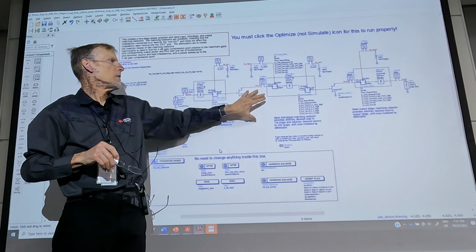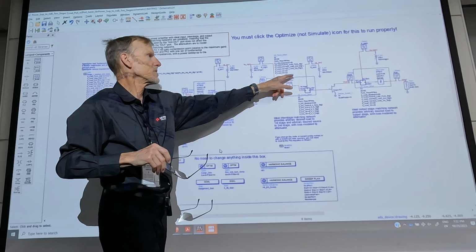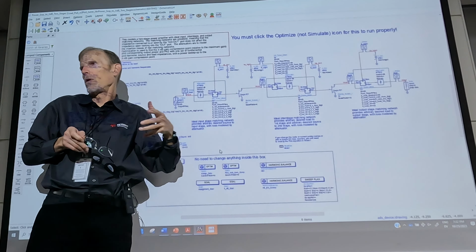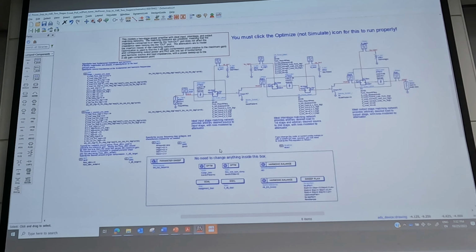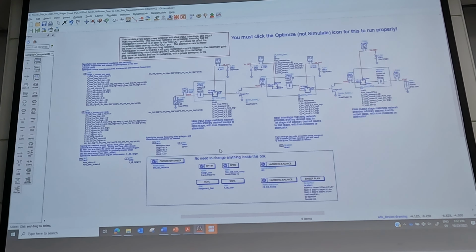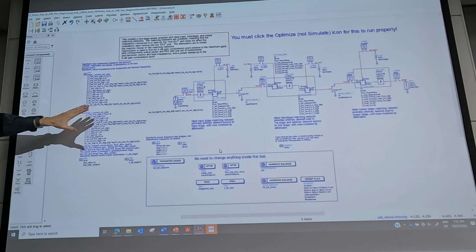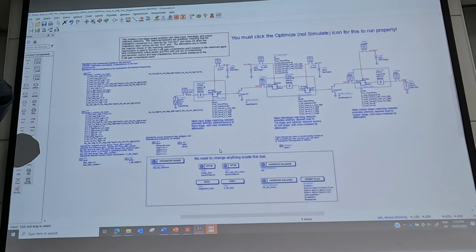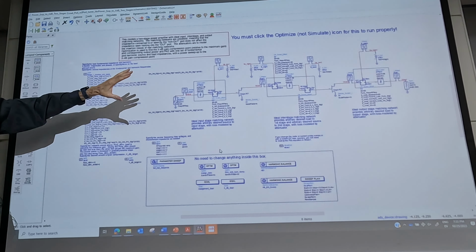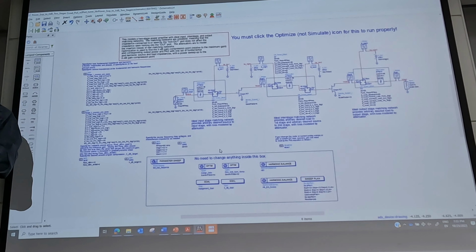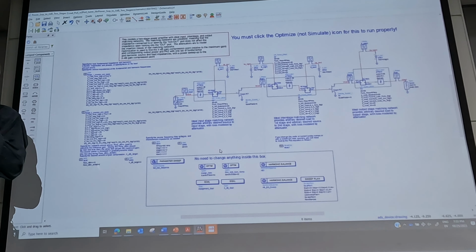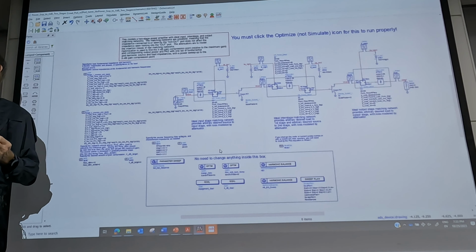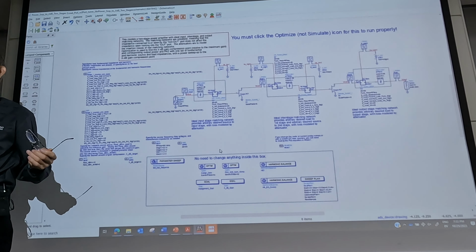Then we have to replace this with a more physical matching network, so the performance is going to drop. It's not going to be as good because we're not going to get the ideal impedances anymore. But at least you could use this to see what the upper bound is. If that's not good enough, then you need to come up with a different design or change the sizes of the transistors or use different devices or do something else. So that's the way I think of it.